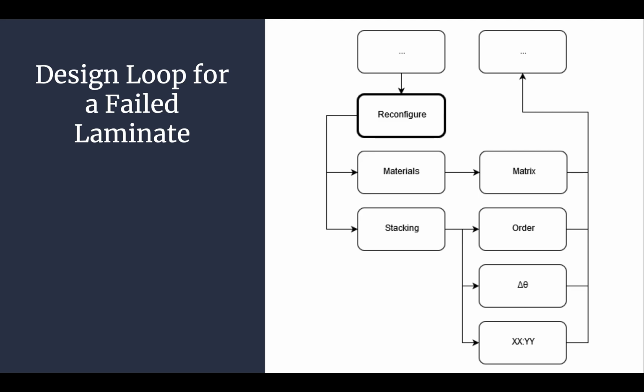Given these material makeups, the majority of our time was spent fiddling with our stacking. That was how we ordered our layers, how we avoided clustering, and how we got a balanced or symmetric laminate. Another consideration was our gradation in angle plies. We tried to avoid something extreme like 0 to 90, and generally we would put in a 45 to keep those gradations and interlaminar forces minimal.